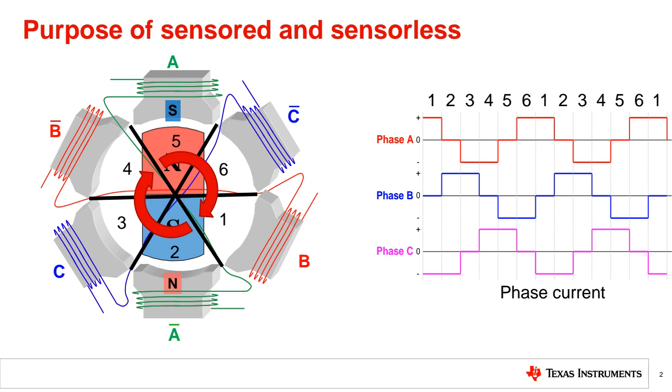Why can we not use sensorless motors every time? I said below 10 percent of the rated speed, sensorless application does not give a very high dynamic response. For example, you cannot track very precise position estimation in sensorless. Why do we say this? Because the sensorless motor control approach depends on back EMF estimation. What is the back EMF estimation?